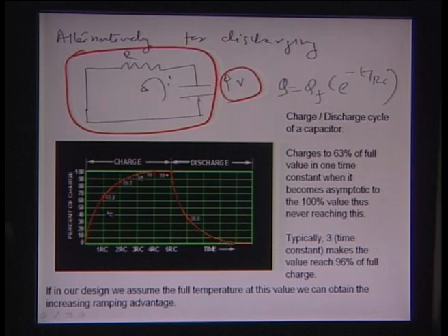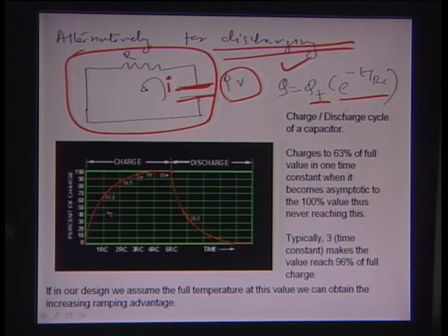the voltage of the capacitor which has been developed over its plates is going to feed the circuit with the current I, and there is a drop across the resistor. So in that case, for the discharging process, the Q becomes QF e to the power of minus t by RC. So at time t equal to infinity, the Q essentially becomes 0, because this is minus. So 1 by e to the power of infinity is nothing but 0. Alternately, at time t equal to 0, the Q is actually grown to its full value QF just before the start of the discharging process.